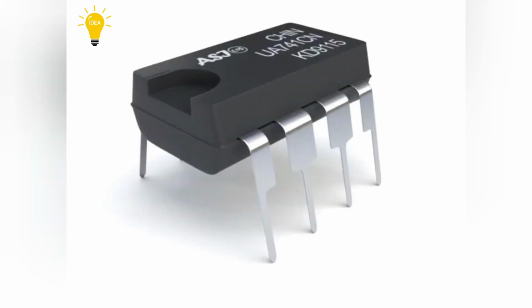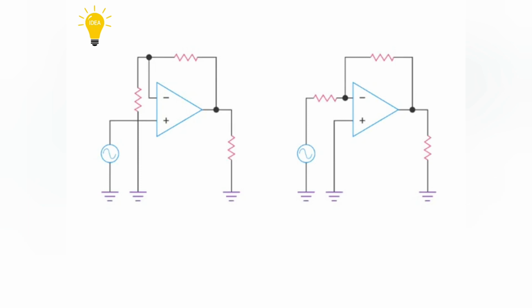Operational amplifier circuits are complex amplifiers compacted into integrated circuits, which makes them very powerful. The two most important operational amplifier circuits are classified as either non-inverting or inverting. For both of these amplifier circuits, a feedback network of only two resistors, R1 and RF, a feedback resistor, are needed to control the gain. We'll first look at the non-inverting circuit.